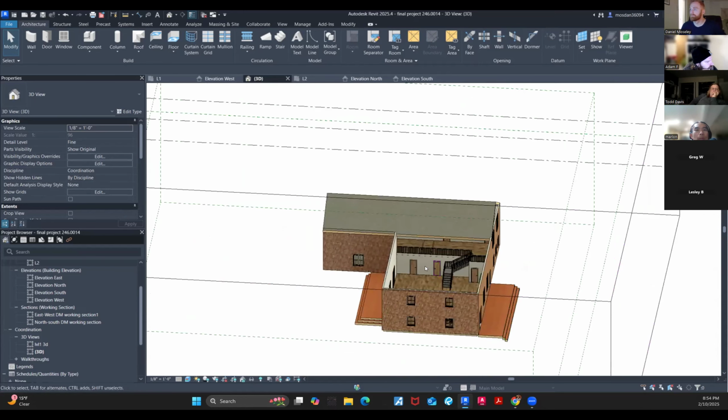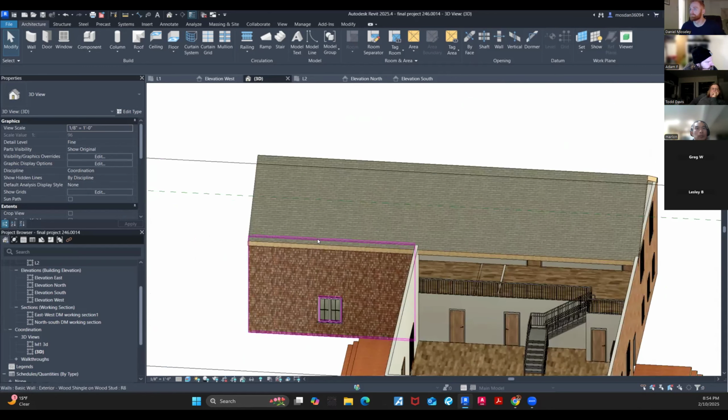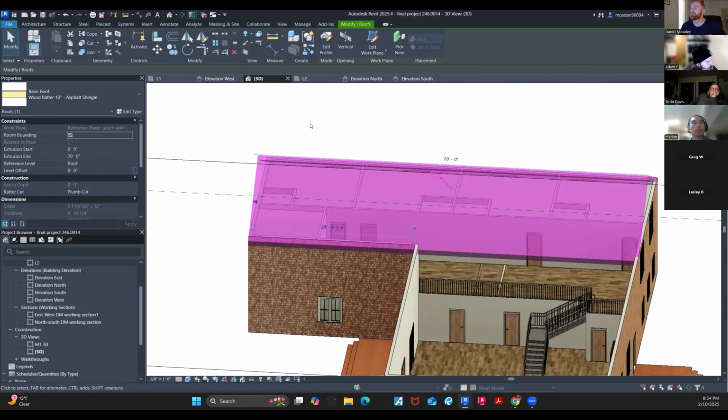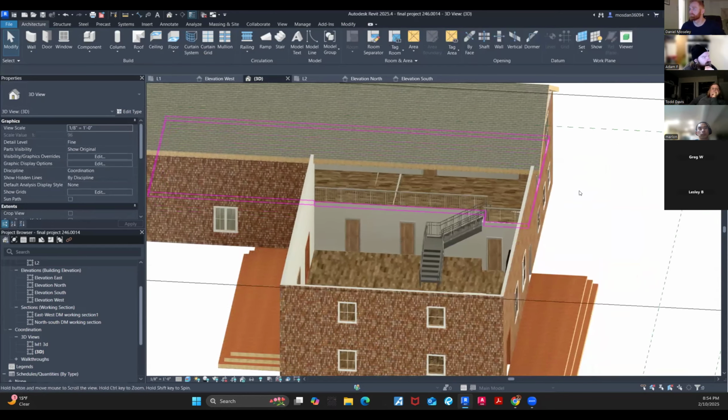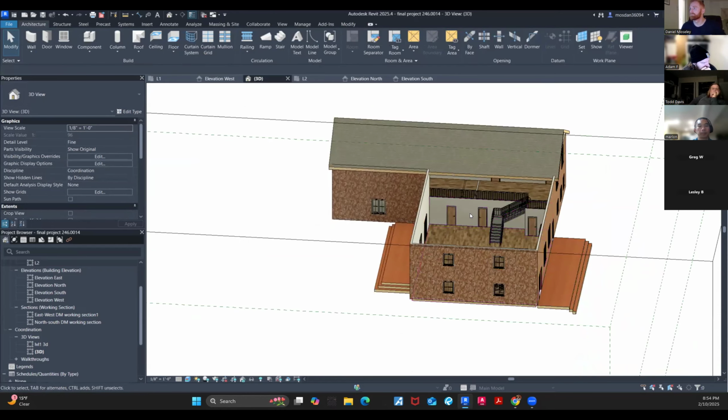Right on. So why don't you go ahead and click on that roof? And you'll get a distance. Yep, it'll come up 70 feet. Go ahead and just make that 72 feet. And again, this is going to stretch you out from the center, so it's going to give you a foot overhang each side. Okay, awesome. So we got roof number 1 kind of built, right?